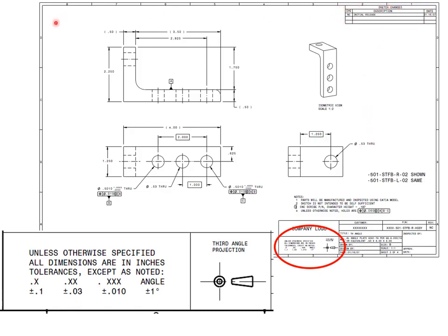When you first release a drawing through document control, it gets processed, dated, and signed off by everybody, your supervisor, etc. Document control will sign off, and it's an official document, so think of it as a contract. Now, if a few weeks later you want to change the diameter of the hole, so here we have a 0.59 diameter hole, it appears. If you wanted to change it to a larger diameter, notice we have NC. NC is the original, which means no change. You could also use a dash or IR for initial release.